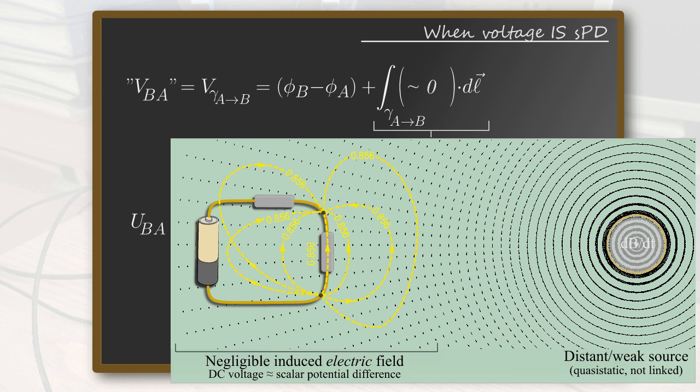This field extends outside the perimeter of the generating coil, even if there is neither magnetic induction dB/dt nor magnetic field B there. The induced electric field varies in magnitude inversely proportional to the distance r from the source, so the farther the generating coil is from the circuit, the weaker is the field.